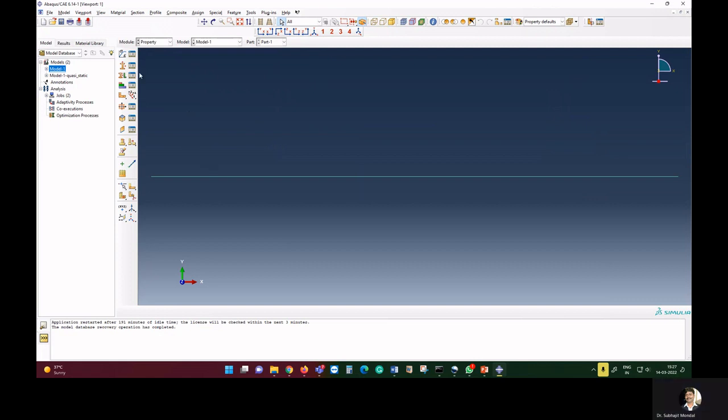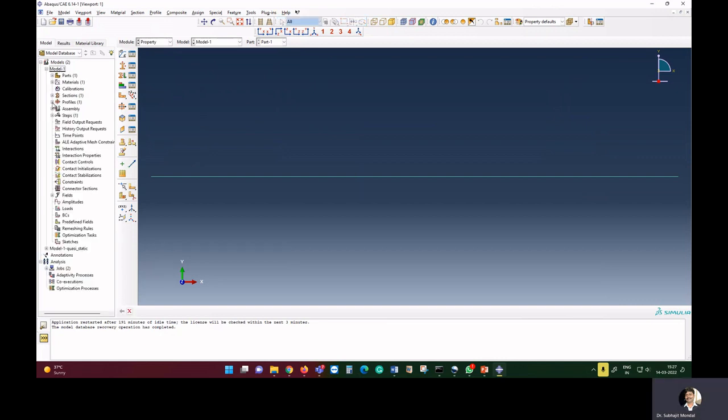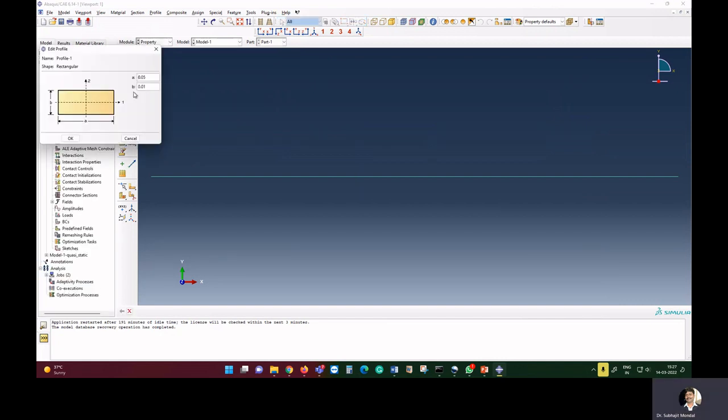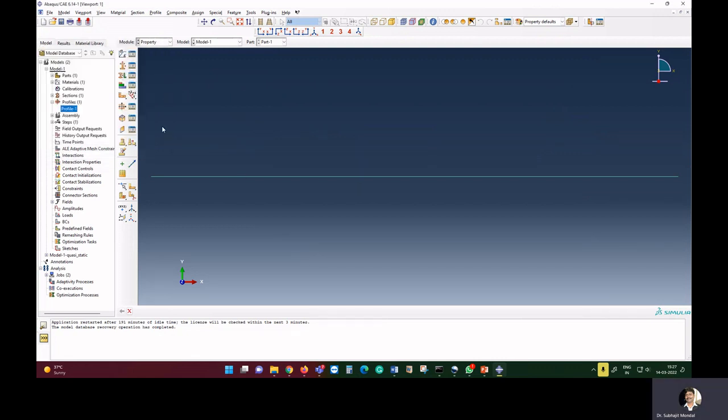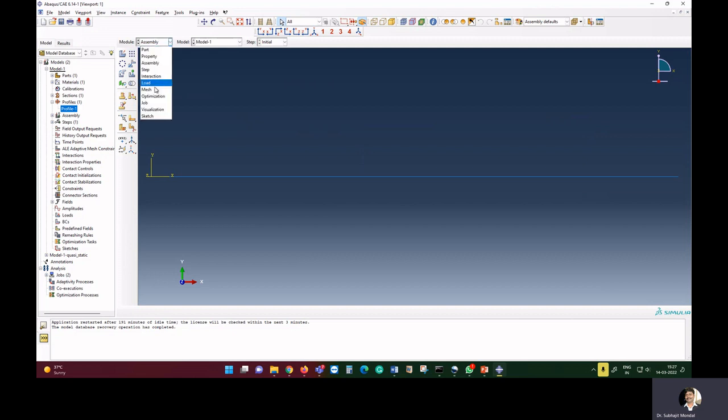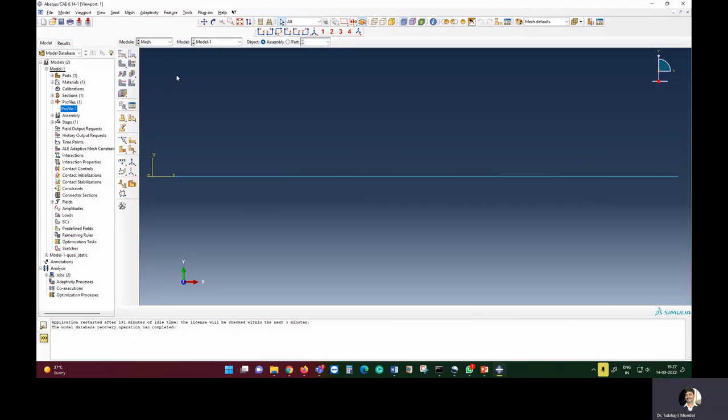And here we define a cross section. If you see from the file, we have defined the cross section with width 15 and depth 10 mm, and thereafter we have assigned it. Next, we define the assembly. Here we have created the instance, and then we have defined it.